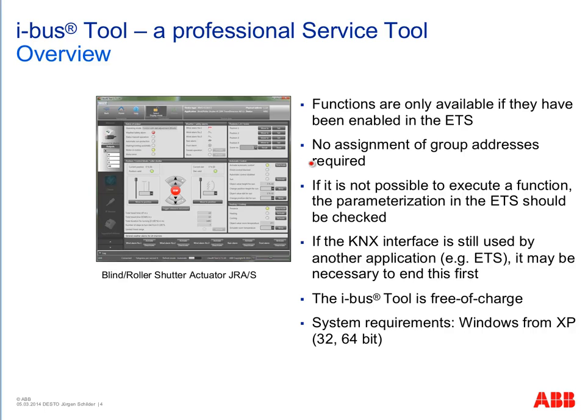The IBUS tool communicates via a special kind of protocol, independent of the group addresses. So you do not have to assign group addresses inside the ETS. You can do it, but this is not necessary.